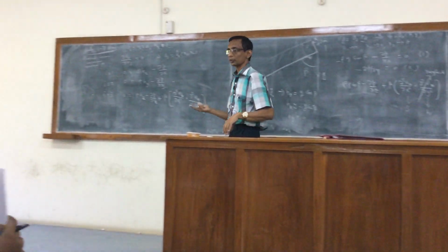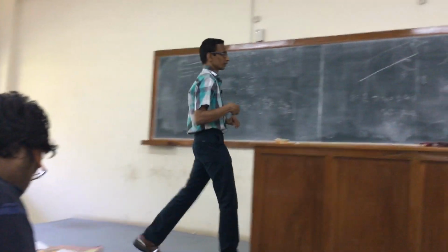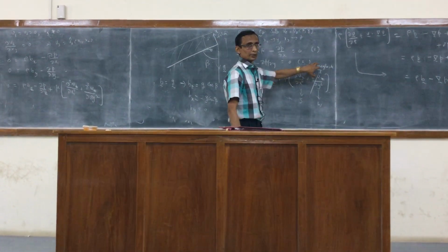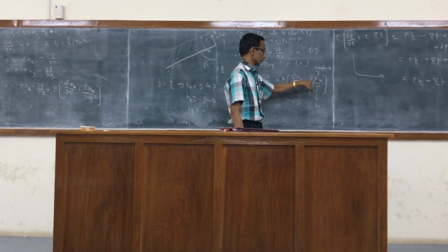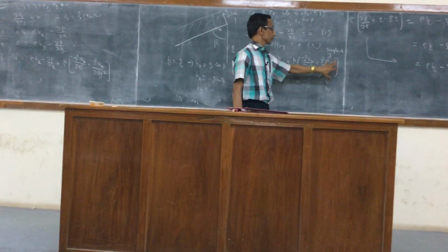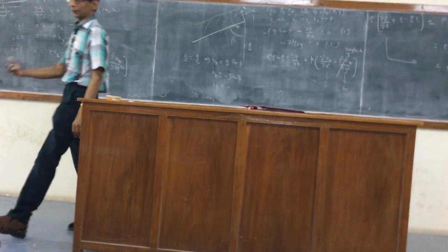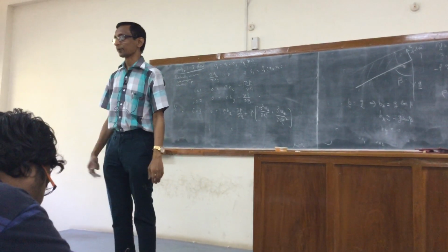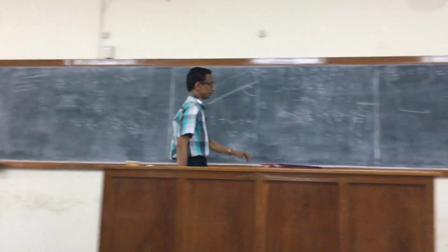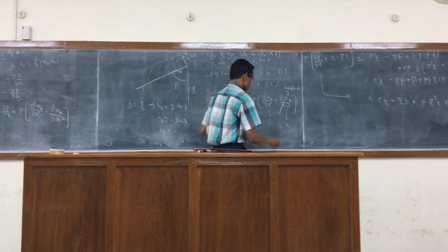So we transform to dimensionless variables. Then you can easily verify that the ratio of these two terms would correspond to delta squared by w squared multiplying this derivative in the dimensionless coordinates. So based on that, you can argue that the variation of Vz in the y direction can also be neglected. That's a further assumption we are making.